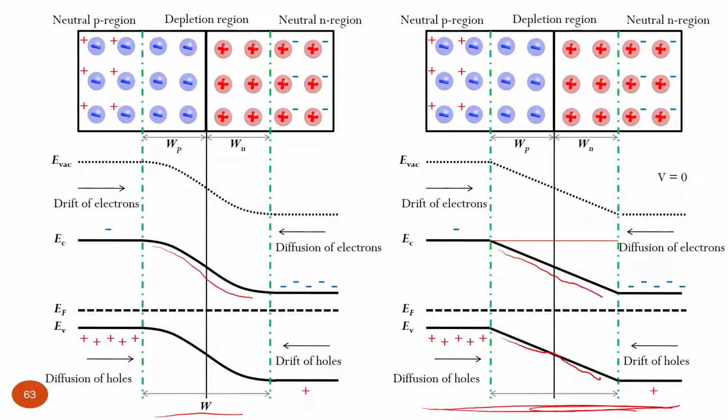So that's quite a realistic energy diagram, quite common for solar cells such as organic and perovskite solar cells, because they usually use this metal intrinsic semiconductor metal device architecture, which works because we have different work functions of the metals, and this difference in work functions creates band bending.